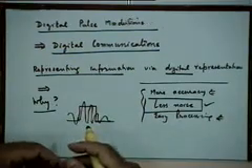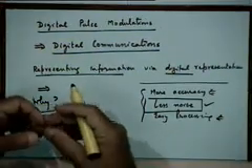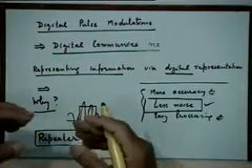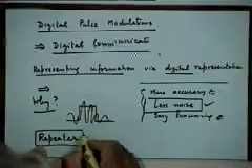So what you can do is make sure that before it becomes too weak and before the noise overrides the signal too much, you recover the signal and make it absolutely a clean signal once again. You regenerate the clean signal, right? Through a simple device which is called a repeater, a digital repeater. Repeater normally in the conventional sense only meant an amplifier. The signal becomes weak, you amplify it, make it stronger and retransmit it, but an amplifier will not do, because an amplifier will amplify both signal as well as noise.